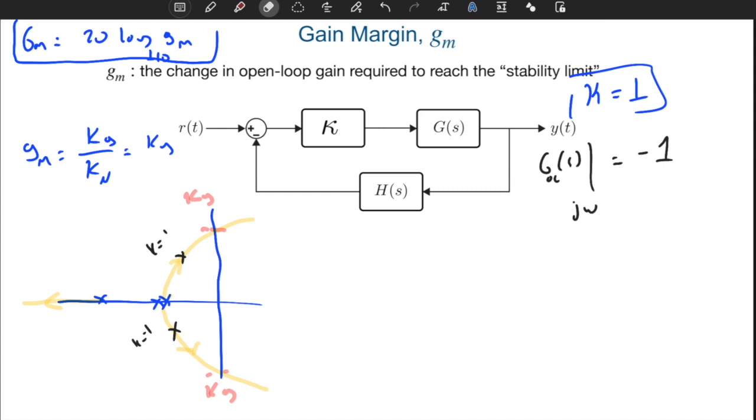That's nice. So what I can do, from the Bode plot perspective, is look at its phase. G(jω_critical) is equal to minus 1. If I look at its phase, the phase of G(jω_c) is equal to minus 180 degrees. So at this specific point, I have an ω_c such that my phase is equal to minus 180 degrees. So what is K at this point?